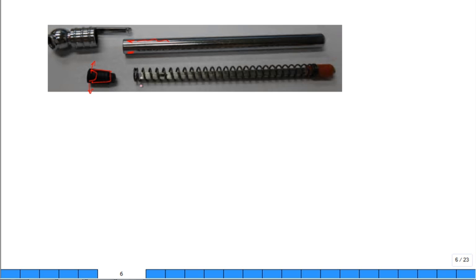Now, it's connected to a spring, and so that spring compresses as the plunger tries to move further down. Hence, if you have higher pressure, the plunger goes further, the spring is compressed more, and from Hooke's law, the force in the spring is the stiffness of the spring times the compression of the spring. It's held rigidly at this location. It's not able to go out. The spring is at the end of it.